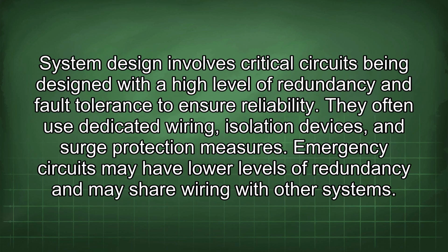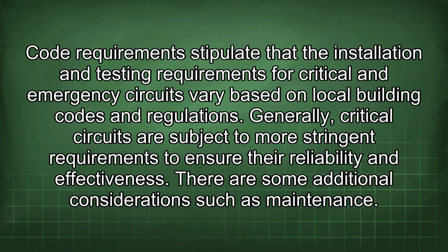System design involves critical circuits being designed with a high level of redundancy and fault tolerance to ensure reliability. They often use dedicated wiring, isolation devices, and surge protection measures. Emergency circuits may have lower levels of redundancy and may share wiring with other systems. Code requirements stipulate that the installation and testing requirements for critical and emergency circuits vary based on local building codes and regulations. Generally, critical circuits are subject to more stringent requirements to ensure their reliability and effectiveness.